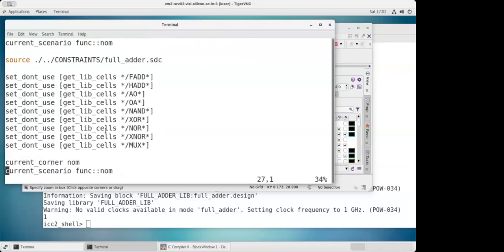Once again you have the control. You can tell the tool, okay, synthesis, whatever you have done, but now I want you not to place these kind of cells in my design. So again you are telling the tool, please don't use these kind of cells, so it is mapped at the synthesis stage. Whatever you have done, if you can redo, then do this particular part. So this time in the file I have already captured a couple of don't-use cells.